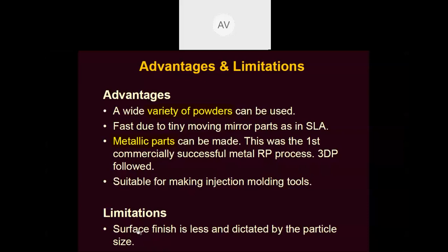The only limitation is that surface finish is limited by the particle size. Here, if you take a fine powder, the surface finish will be improved, I think, because surface finish is limited by the particle size. While fusing, the particles get bonded, and at the last upper layer you will see the particles fusing, and some of them will be outside.